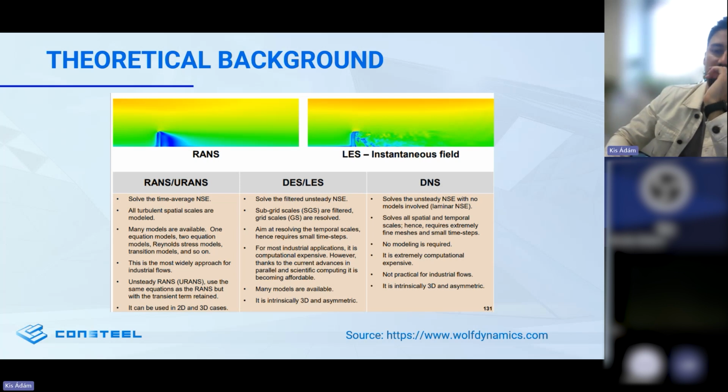of turbulence scales. And it is intractable for the complex flows around the building. So it's really hard, or almost impossible, to calculate with current technology. But the best compromise is probably the large eddy simulations, which compute the turbulent eddies down to a threshold size, below which the Reynolds averaged Navier-Stokes is used. But again, the question remains the same.